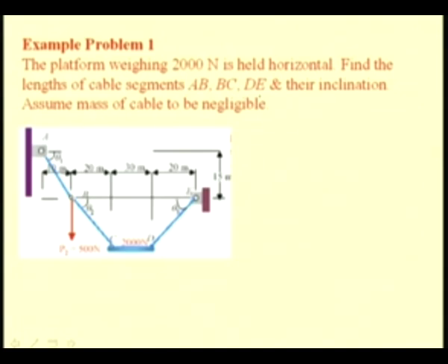The unknowns for this problem are the end reactions, that is Ax, Ay and Ex and Ey, as well as the forces at this point C, that is Cx and Cy. Because if we know these forces, that is Ex and Ey, then dy and dx are also known. So, the unknowns for this problem are 6, that is the horizontal and vertical components of forces at A, C